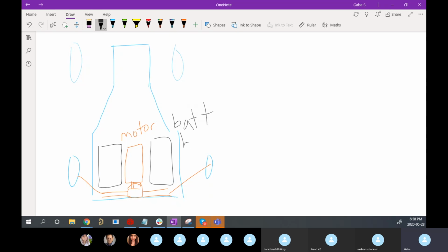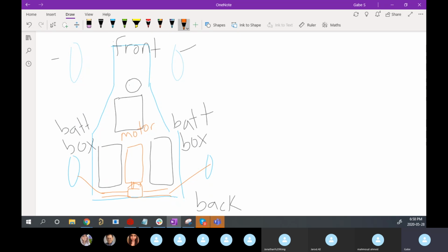So we have one battery here and one battery here. So we call them battery boxes. Just a reference, this is the front of the car. This is the back. These circle things I drew are called wheels. And then the driver sits here. So steering wheel is kind of here. And then the driver sits right here. So because our battery boxes are split, and that's where a lot of the circuit boards are held. So for example, the BMS is in one of these. I think it's the right one, if I remember. BMS is in here. And remember our thermistor expansion board was 3 boards.